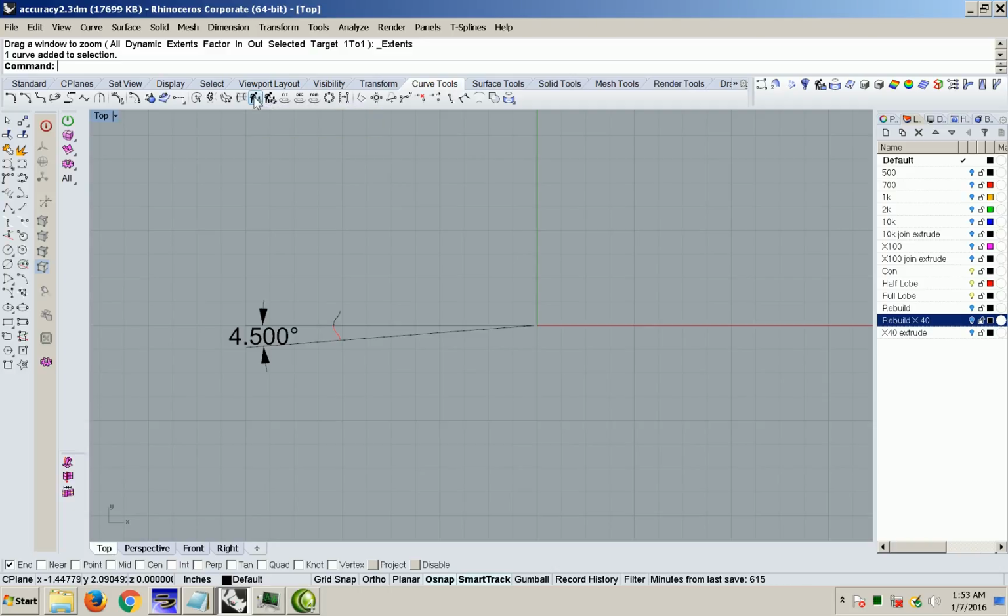The final step to turn the profile into a 3D model is to use the Surface from Planar Curves command to generate a 2D surface and then extrude the surface with the extrude face command.